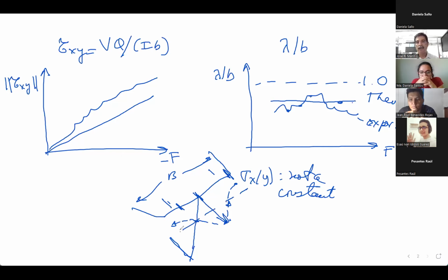So this is the value from pure bending theory, and for this you use from here until here, full B. You apply DNV theory, so you don't take full B, but you take a percentage of B. That's the effective breadth. So you reduce inertia, and the result is going to get this value here automatically. And that's the concept of effective breadth. So you don't need to calculate this. If you apply DNV theory, this is what you are going to obtain.